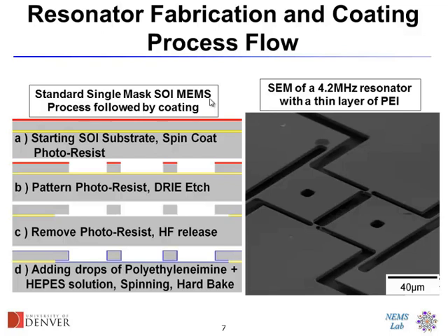CO2 is kind of acidic, and then you have these amine groups which act like a base, and they can absorb CO2. So to coat the resonator, this was probably the most challenging step in the process, because these are really sensitive, tiny devices. If you look at the dimensions, it's about 50 microns across. So you have to do it in a way that you don't disrupt the operation of the device. So what we did was actually pretty simple. We just diluted the polymer in a solvent and spin coated it onto the resonator.